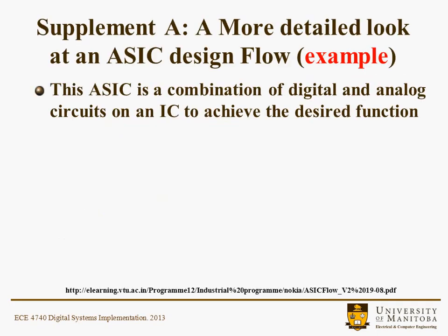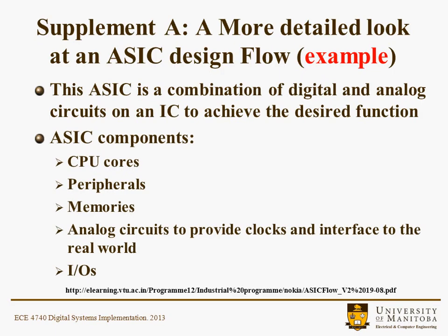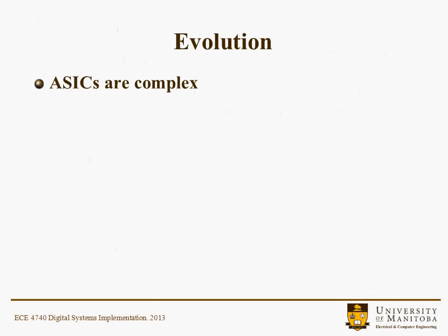Anyway, this is a supplement. It's a little more detailed look at an ASIC design flow, and it's just a representative high-level overview of an ASIC design flow. Every company would typically have their own. This particular ASIC is a combination of digital and analog circuits on an IC to achieve the desired function. The ASIC components might be CPU cores, peripherals, memories, and analog circuits to provide clocks and interfaces to the real world, and of course IOs.